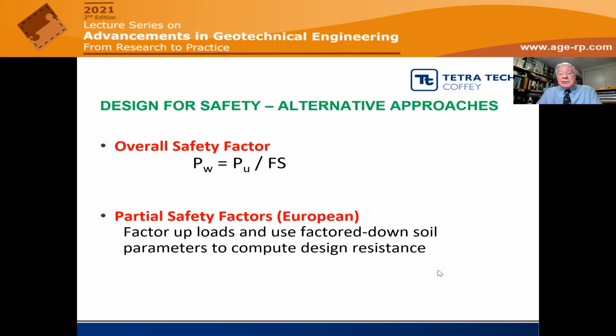In recent years, the Europeans have come up with partial safety factors. So they've factored up the loads to allow for uncertainties in the loads and factored down the soil parameters, that is the strength parameters, to compute the design resistance.